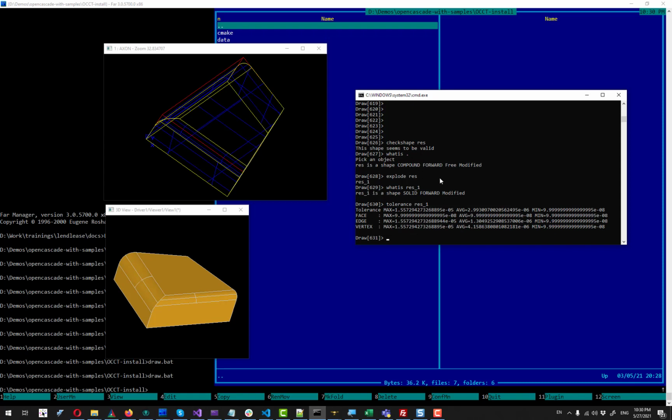So now I am ready to go. I am ready to export this solid to a step file, and for that I'm going to use this stepwrite command. And here I need to pass a couple of arguments. The first one is a mode, because I can export my resulting solid into different entities of a step file. And actually, if I do not care much about this topic, then I just pass a, which means as is.